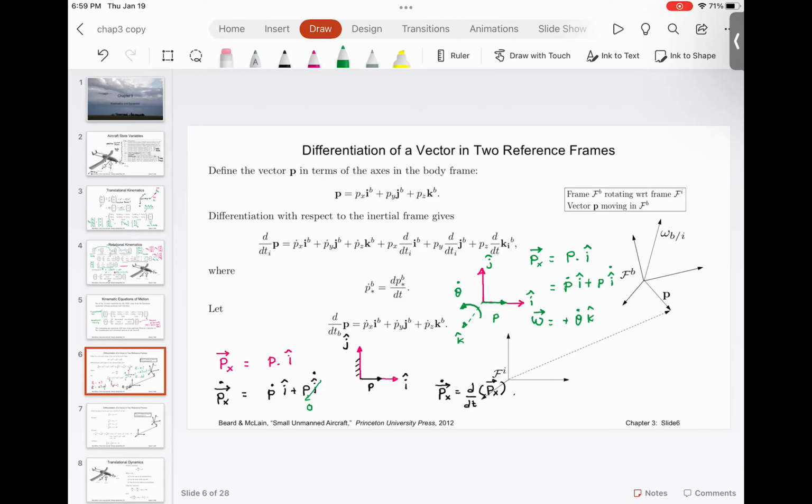Remember velocity, angular velocity. So it has magnitude and it has direction. You agree with me? Whenever you have a derivative of vector, whenever you have a derivative of unit vector, the rule is take the frame angular velocity and cross it with the vector.